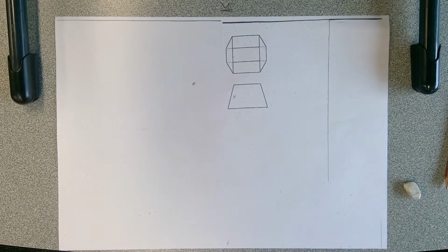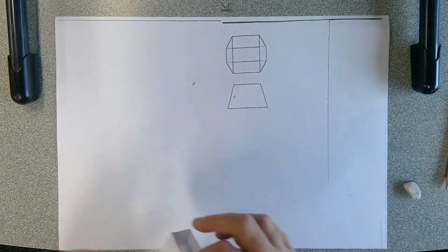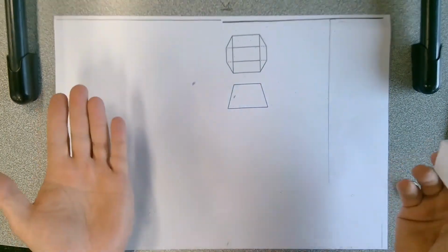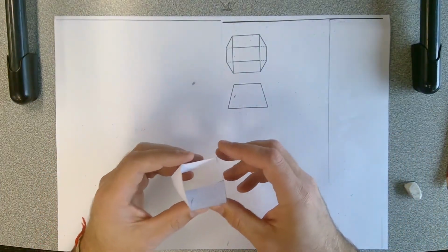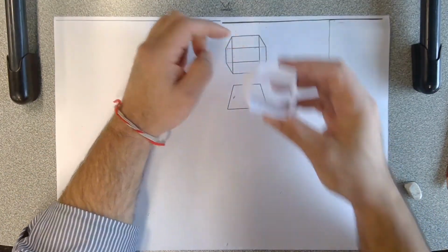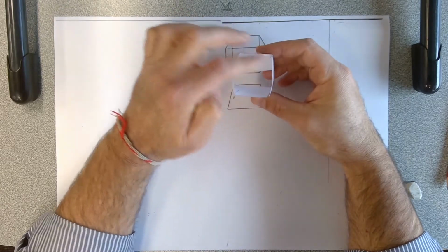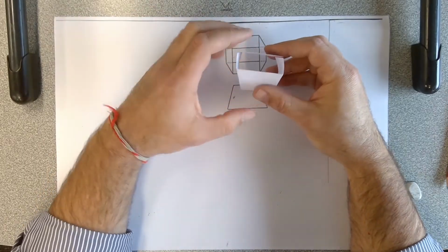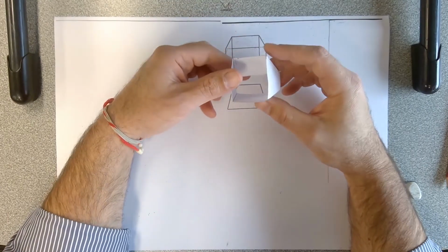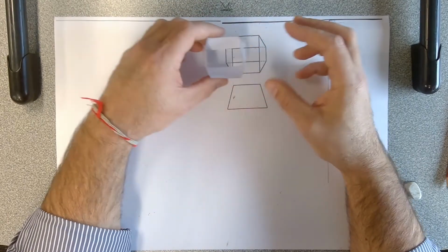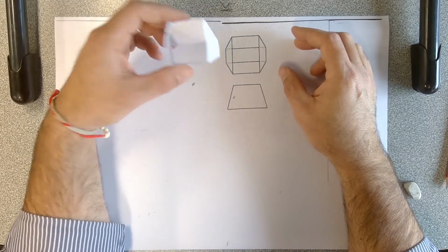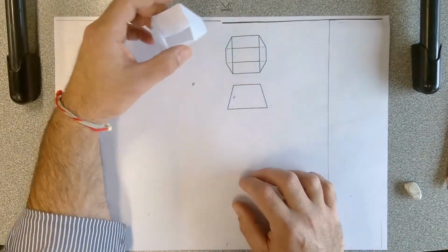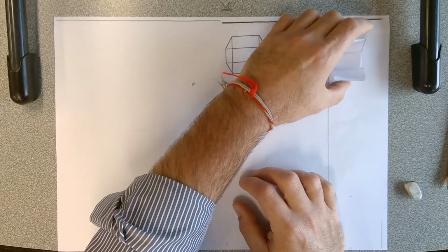Okay, development by triangulation. This is basically taking a drawing and turning it into a flat shape that you can fold to make the object. Now this is going from a square, which you can see here, to a rectangle on the bottom. And I actually made this shape that you could have cut out of, say, sheet metal to make a hopper like this that goes from square to a rectangle using this process of development of a transition piece.